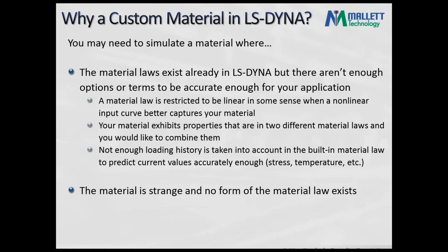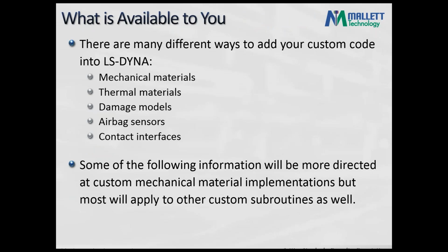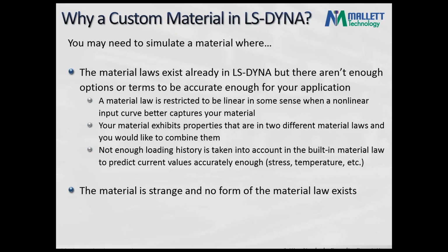And sometimes your material might just be strange, and there's not really a material law that exists in LS-Dyna, but that probably won't be the case. I'll say a little something: LS-Dyna in its inception was kind of geared towards the auto industry. I know it's expanded a lot since then, but some materials that might be a little out there and weren't relevant to auto industry applications might not have all the options that you need, and you would have to come to this custom material.